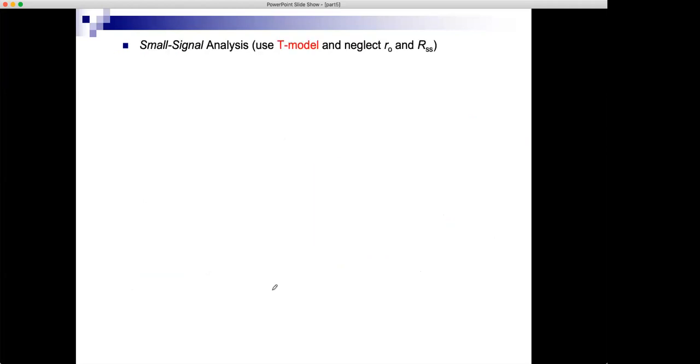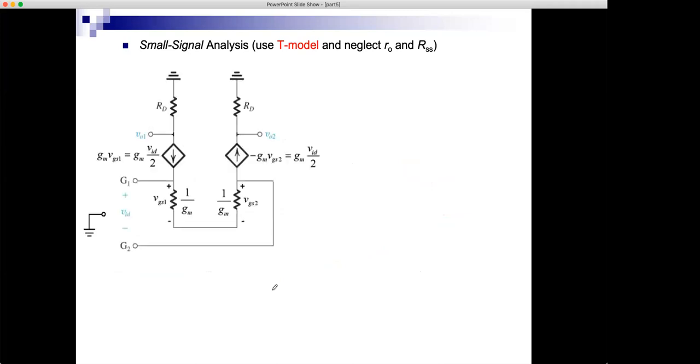Let's extend the analysis using what we just learned, that I have a virtual ground. You see here the gray ground. It's a virtual ground. No signal. We see no signal here. And remember, we see no signal here when I have differential input. So V plus VID over 2 here, minus VID over 2 here.